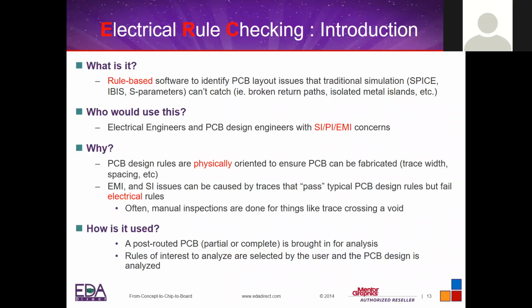Underneath this checking, there is a SPICE engine that runs the simulations and detects these kinds of electrical issues and reports to you if there's any electrical violation. So this is like doing simulation without you being involved in setting up the simulation and looking at waveforms. You submit the board, you specify the rules, and it goes through and identifies these types of issues.